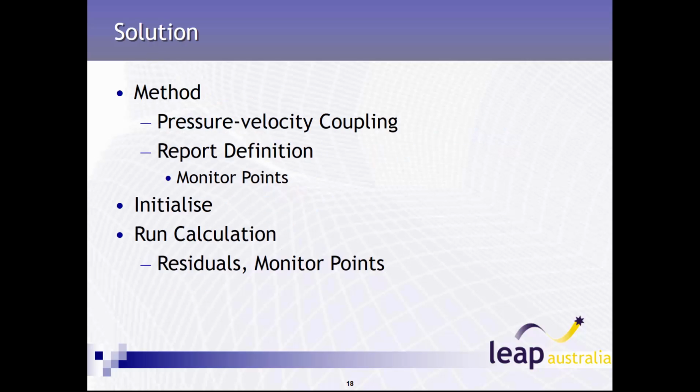our situation. And then in the Solutions tab, we'll be using the pressure velocity coupling scheme. Now, a segregated solver first solves momentum equations using a guessed pressure and then corrected. Due to the guess and check nature, a large number of iterations are required. Using a coupled solver, which solves pressure and velocity in a single system, reduces the number of iterations required for a convergence to a steady state.